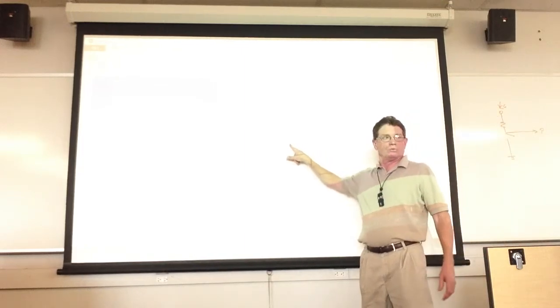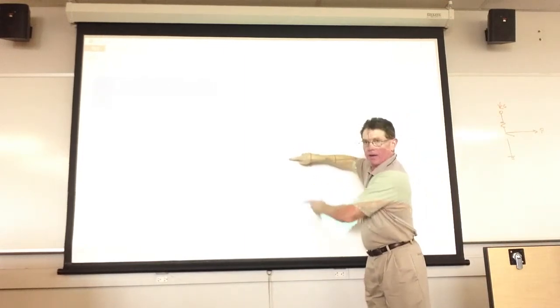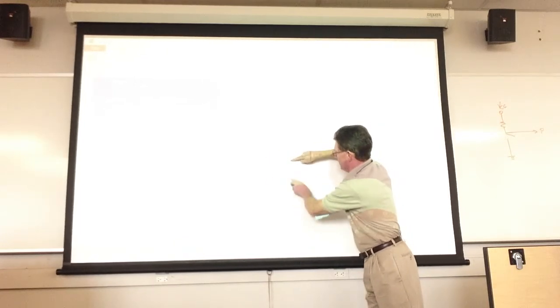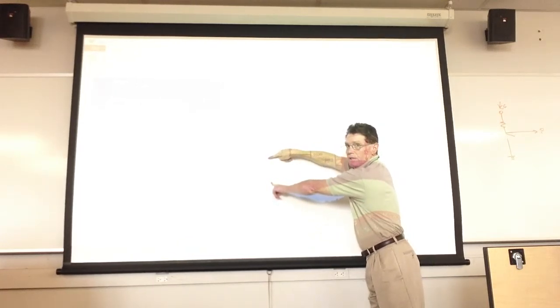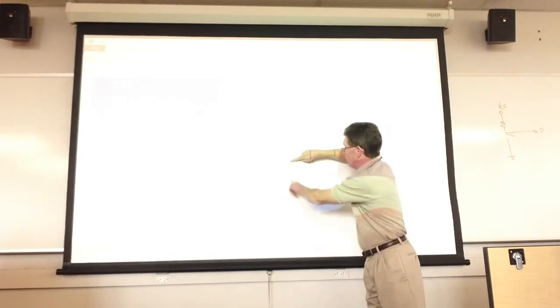Right now I have the Fluke meter on that port, and it's at VCC, which is 3 volts on that port. So I've got 3 volts sitting on there. Again, the switch is open. This is sitting at 3 volts. I basically took that with the switch open, going right to the meter, and it's reading 3 volts. When I throw this switch down, what's the meter going to read?